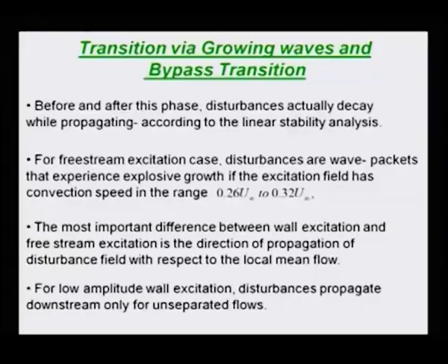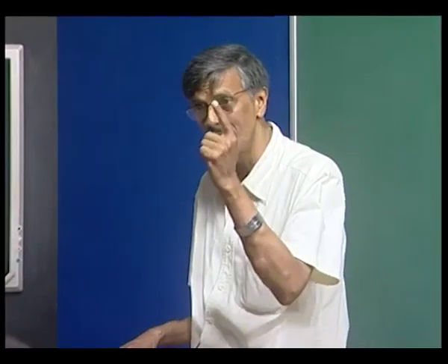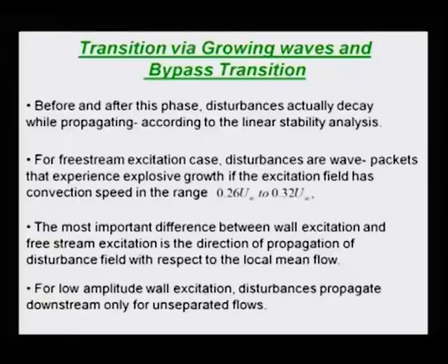So we're emphasizing again, free stream excitation is equivalent to upstream propagation with respect to the disturbance. So with respect to an inertial frame, it still may look like going downstream, but with respect to the disturbance in the free stream, it actually moves upstream. Okay.